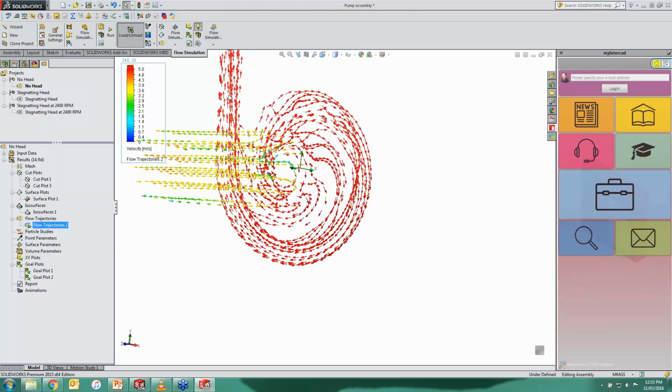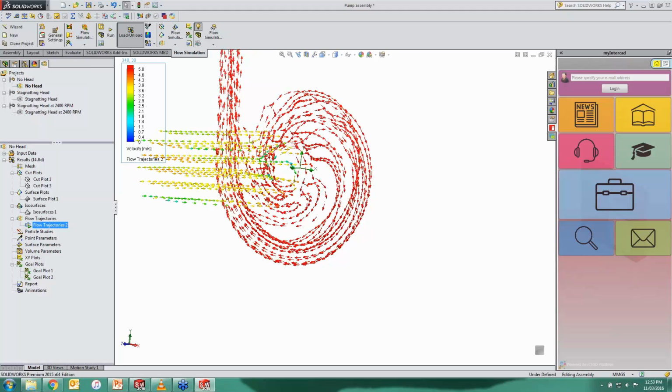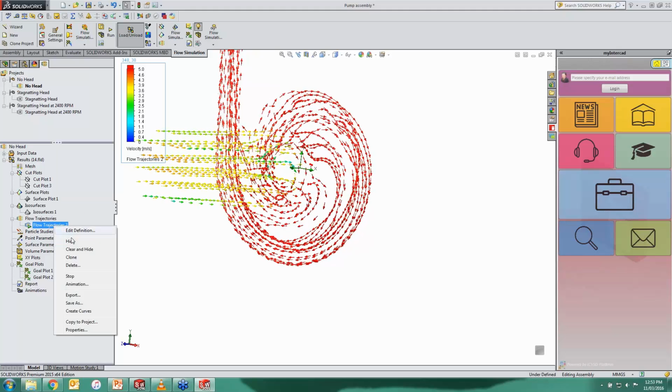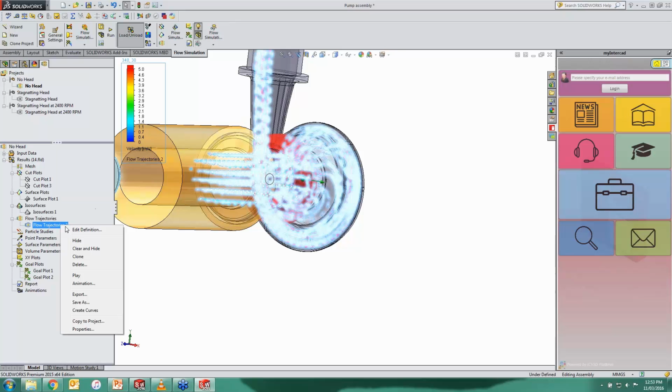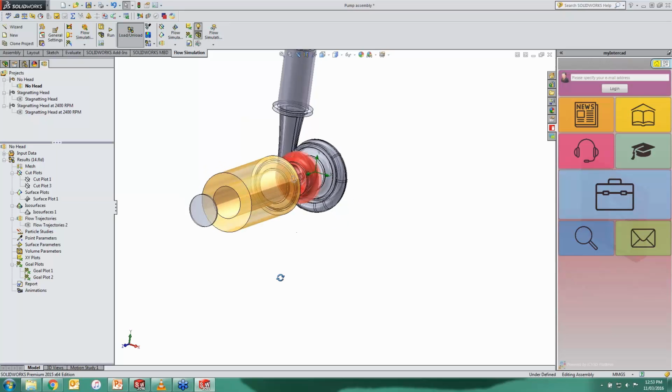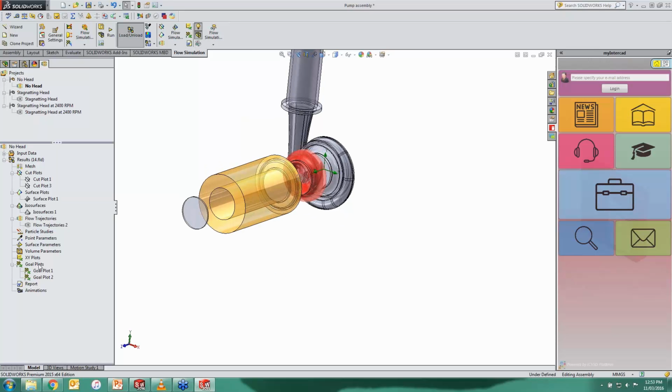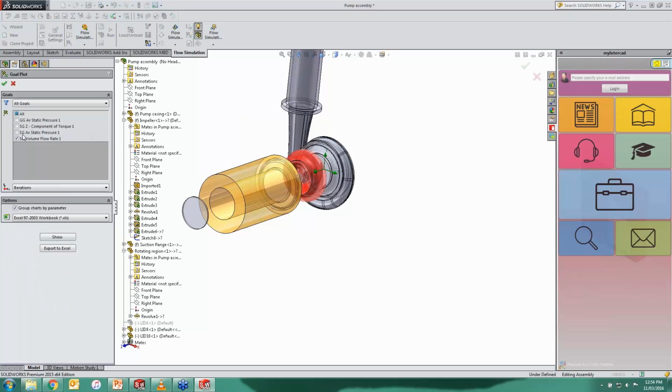All right, this is almost it for the 3D presentation of the result, but in many cases we would like to know exact values and make measurements on exact points, surfaces, and so on. As we said before, one of the tools we have is creating goals, and later on we trace the goals here. What I've done is insert a goal plot, right click and insert, and you can see the list of goals I have, such as volume flow rate of exit.